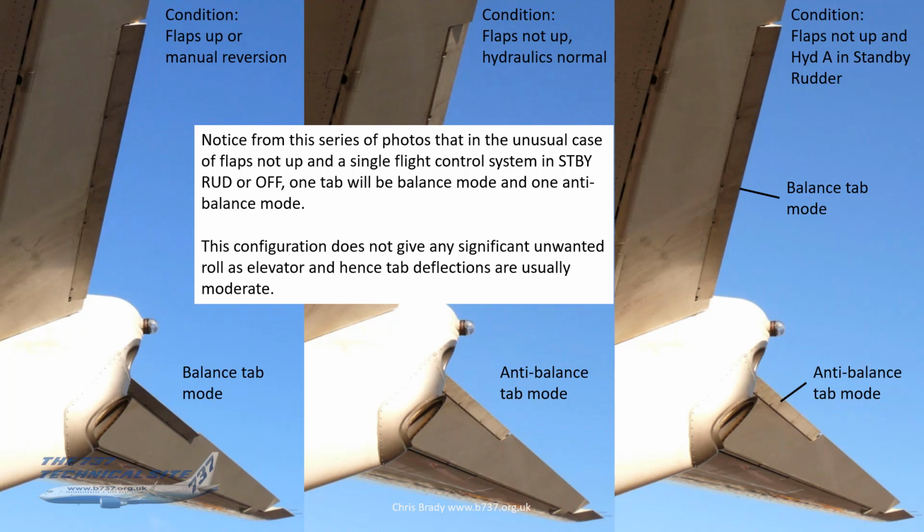Now, I can tell you again, because I've done this in flight, it doesn't actually give you any detectable unwanted roll, as the elevator and the tab deflections are usually quite moderate, particularly when you're with a hydraulic system down or in manual reversion. But I just thought that was interesting, and a great demonstration of the functionality.